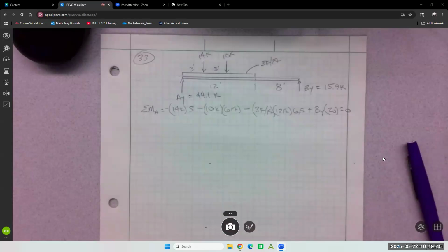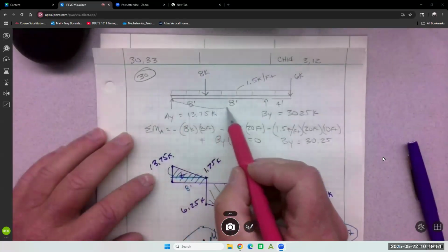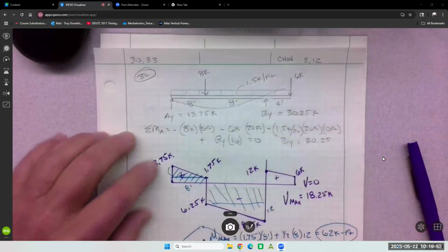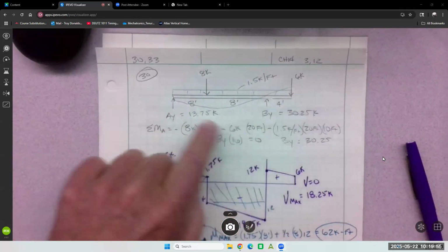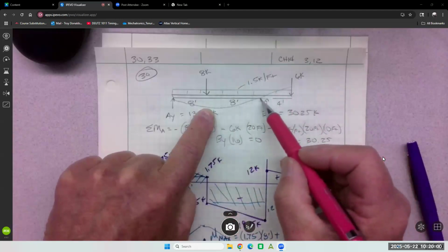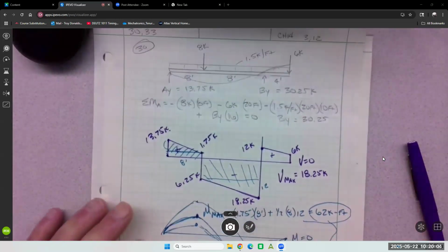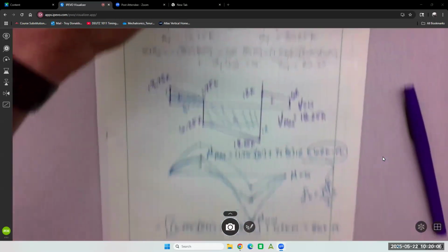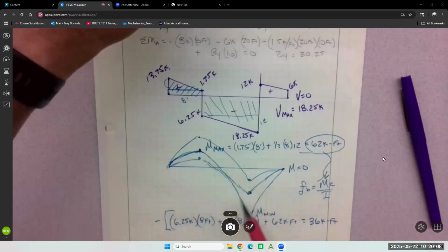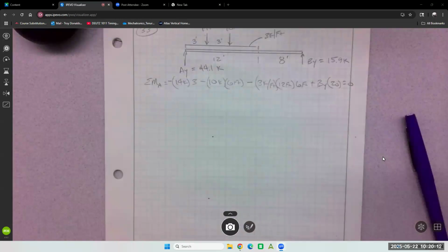So just some clues. This one had a deflection curve that looked like this. So deflection is how it is going to move around, right? So you can see that the concavity of the deflection is up, and then the concavity of this deflection over here is down. That's how we end up with this positive and negative moment thing. The deflection curve goes in like an S shape.